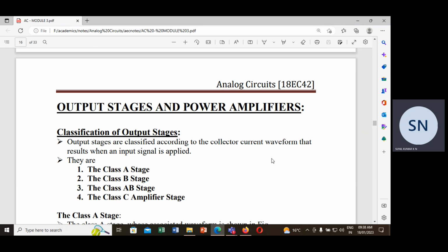So input, if it is a microvolt change between the two input terminals, if it is small, typically a 5 microvolt difference, the gain we get is more. It will be in terms of 10 power 6 without any feedback. That means if you consider feedback from output to input, the gain is going to reduce.